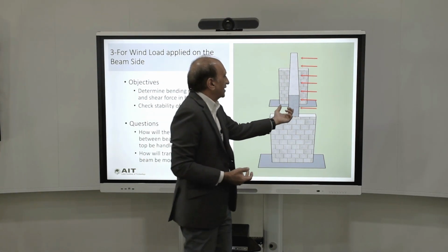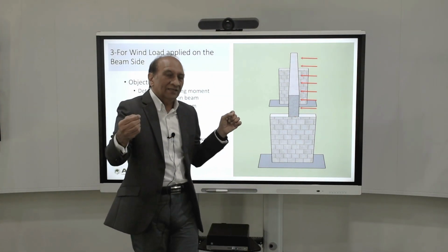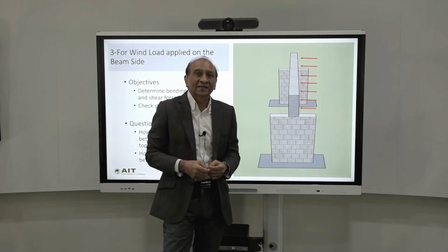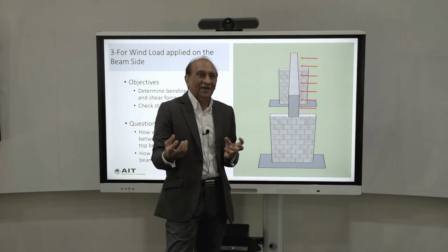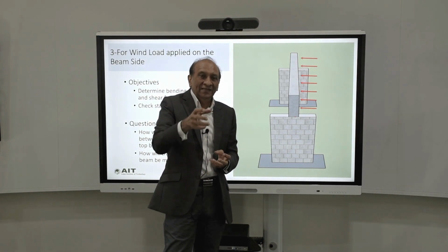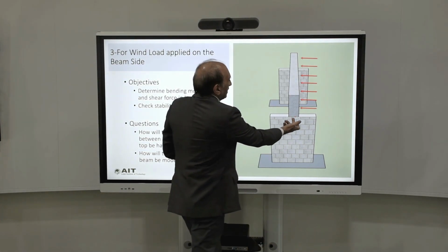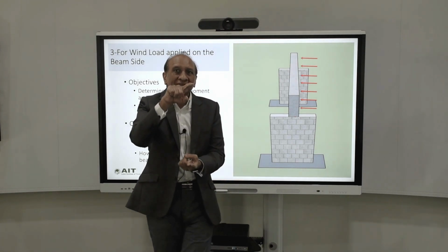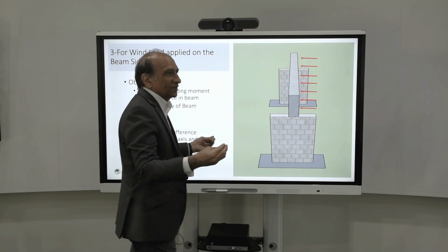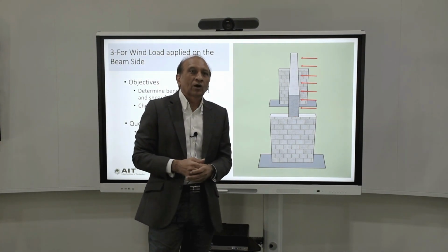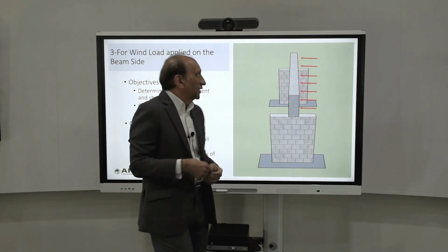Also in reality, this beam might topple and overturn over the wall, but our center line beam model will never tell us that can happen, because it is representing the beam at a center line which is supported on both sides, so it cannot topple, it cannot rotate in that way. Even if it can rotate, it can only rotate about the center line, not about the top of the wall, which is far from the center line. So that means now our traditional simply supported roller pin model will not work in this case, right? And we need to go beyond that.